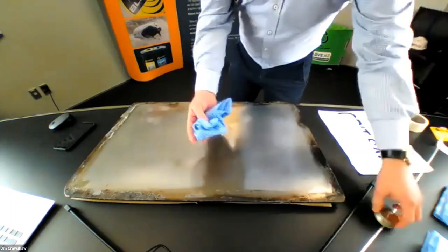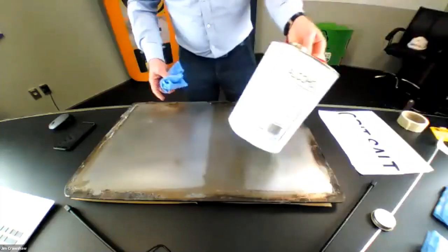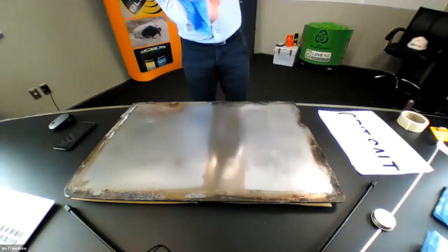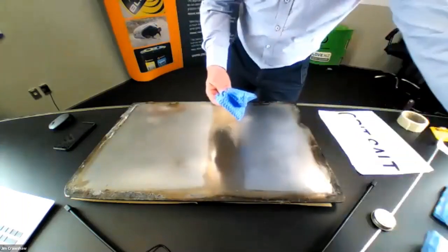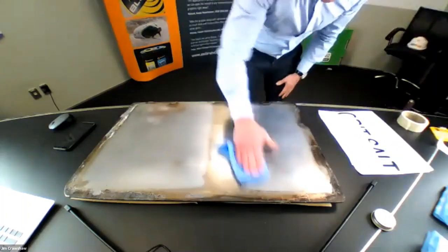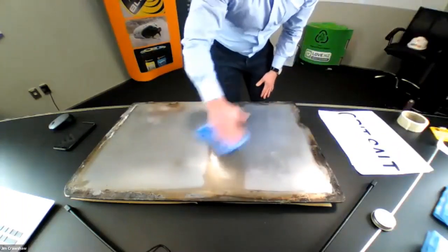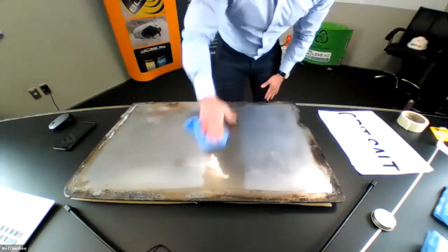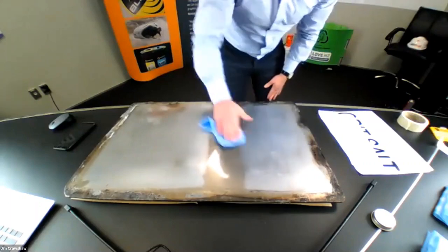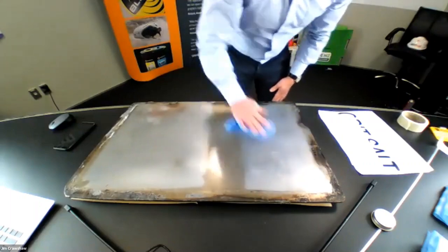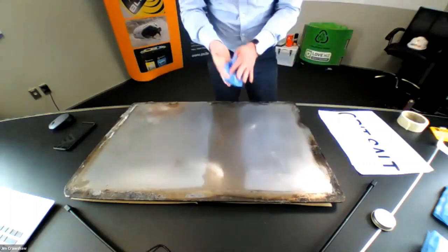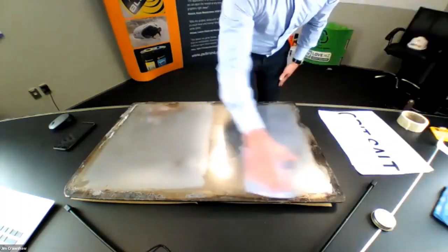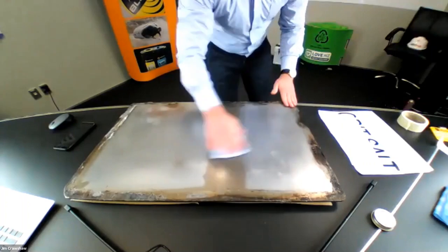So what I'm going to do now is clean this off with a bit of IPA, or isopropyl alcohol. You can use your release agent remover, whatever you use, but I find this works really well. I'm just going to give this a good scrub in the area, making sure we've brought all that release agent off. I'm pretty confident we've got most of it there. And I'm going to use another dry rag just to make sure our surface is nice and dry.